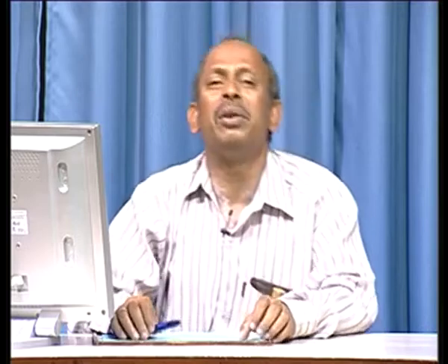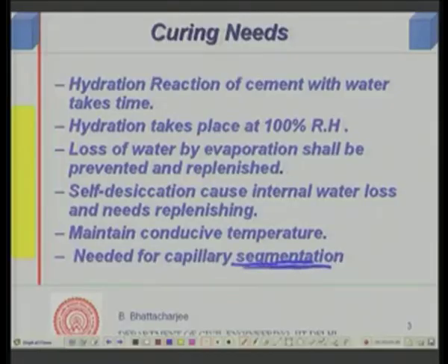So, segmentation of the pores, that is separation of one pore from another, so that they do not remain interconnected, is most important from the durability point of view of concrete. This capillary segmentation is very, very important.